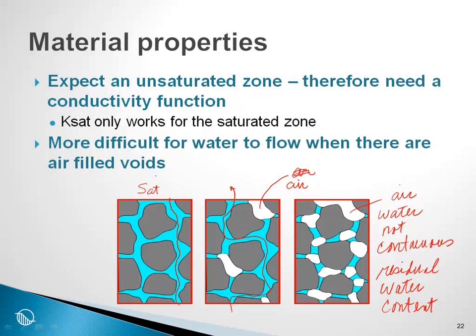So we move all the way from the saturated condition to the residual condition. And all of this depends on the degree of saturation or on the amount of air voids that are within the sample. And to repeat, this is the easiest and this is the most difficult. And the degree of difficulty we describe with variation in the hydraulic conductivity.